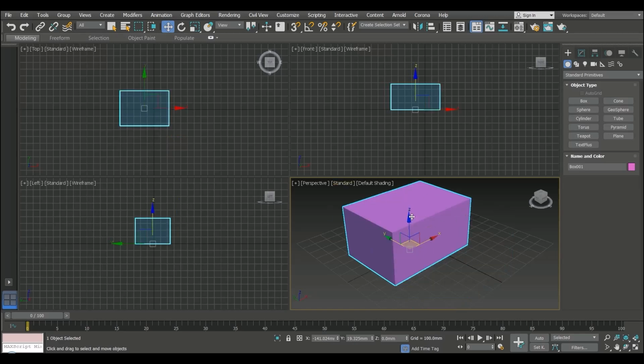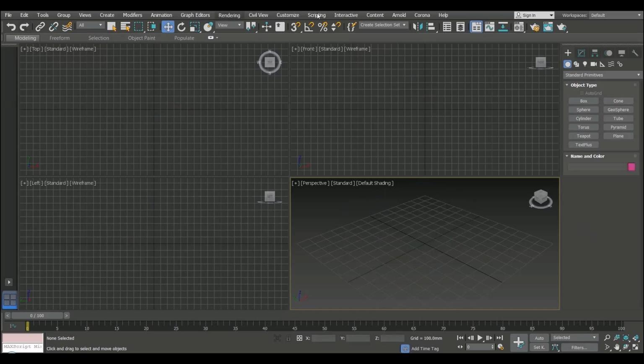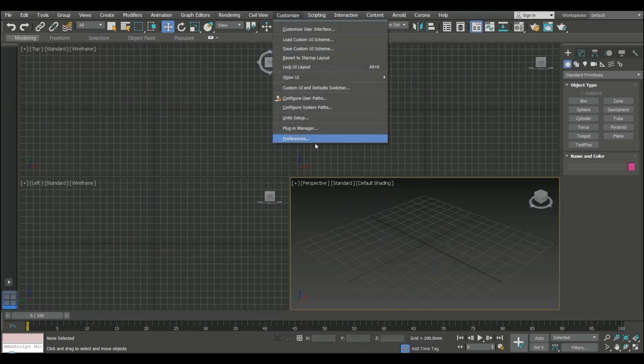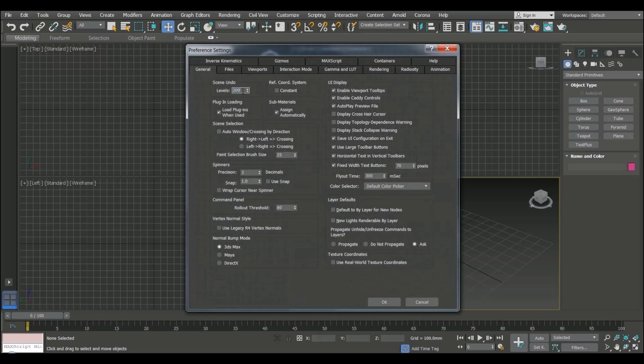will go back, and on the default it will only go back 20 times, but now it will go back 200 times. So this is going to use your RAM, but it does mean if you go off on one and start creating things and you want to go back, you can press undo 200 times, which is pretty handy. So let's go back to the preferences. So make sure that's on.